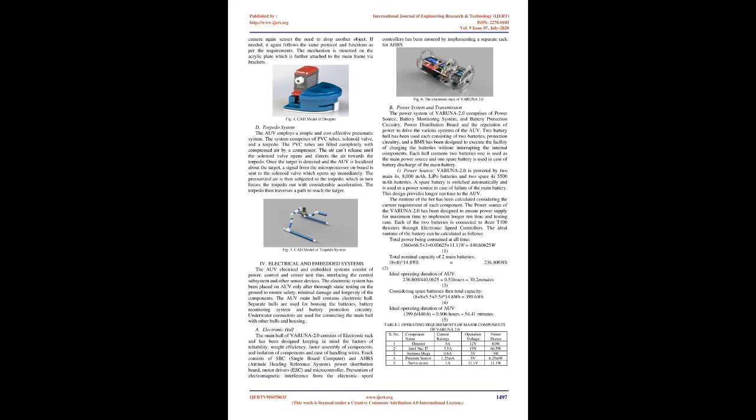Once the target is detected and the AUV is localized about the target, a signal from the microprocessor on board is sent to the solenoid valve which opens up immediately. The pressurized air is then subjected to the torpedo, which in turn forces the torpedo out with considerable acceleration. The torpedo then traverses a path to reach the target.